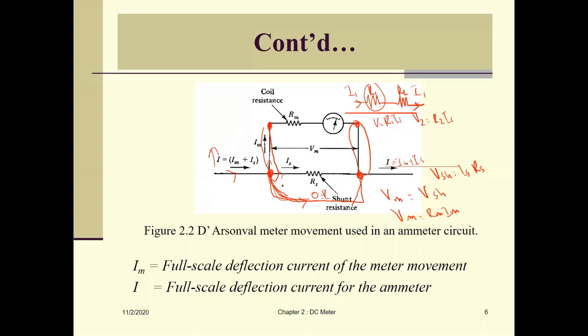That's why if you want to measure the current, for example this Im here, you can put it like this. This one will be connected to this one. This is in series. If you want to measure the Rs here, Is here, you can put our digital multimeter like this, one point here and another point here. So current will flow through this one, our ammeter, like this.